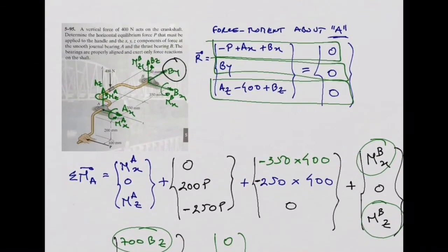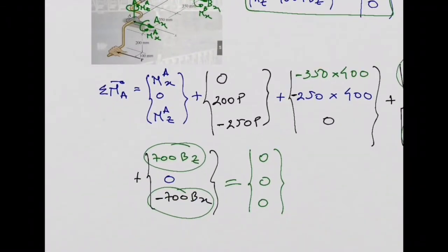First, the difference is on the reactions, right? Because Bx and Bz, they are forces. Mbx and Mbz, they are moments. So they're both acting. That is the main difference, right? The moments, they constrain the rotation of the crankshaft, while the forces, they constrain the translation. Okay? But of course, when you have a force multiplied by a distance in perpendicular direction, that will give you a moment as well. That's what we are calculating here now, okay?